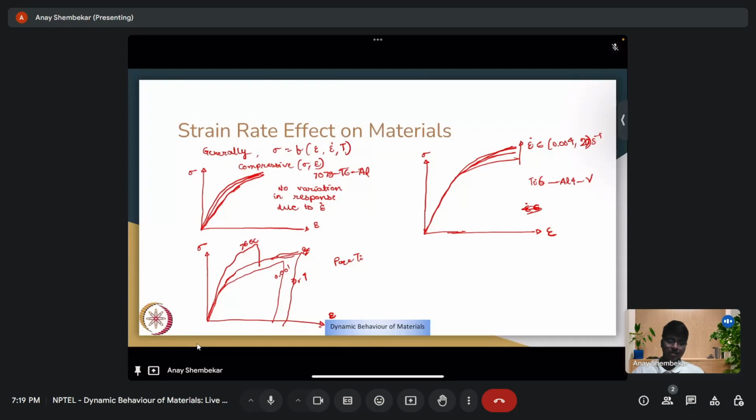So here we see that it goes to a particular strain and then stress falls down for lower strain rate values. Whereas the peak strain that it achieves for very high strain rates seems to be decreasing. So the peak stress has increased, but the maximum strain it can go to has seemingly decreased. Another in this series of stress strain plots is tantalum.